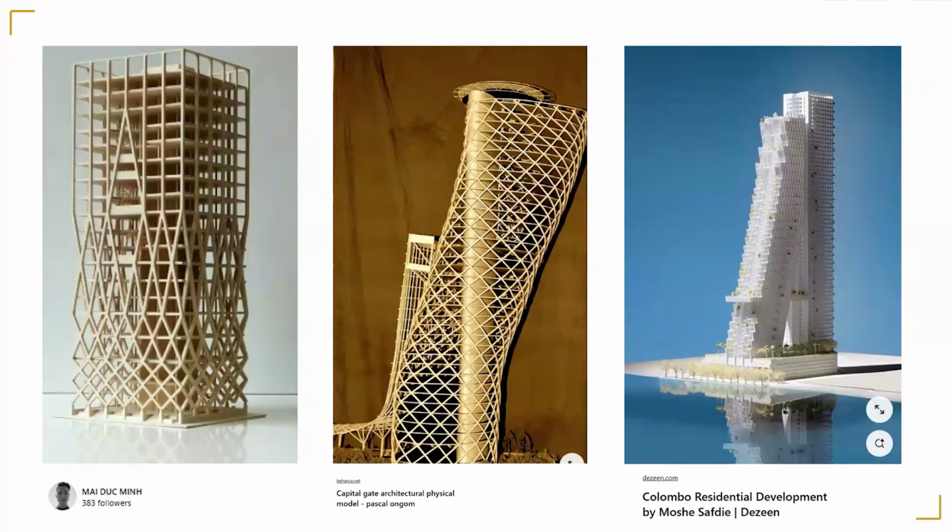So when they make this building, in reality, after you finish the building, it will tilt like this because the weight is out of balance, right? So they made it like this. During construction, it was not made straight. Because of the construction sequence analysis, they determined how much inclined they should make it, so that when the building is finished, it will be straight, right?